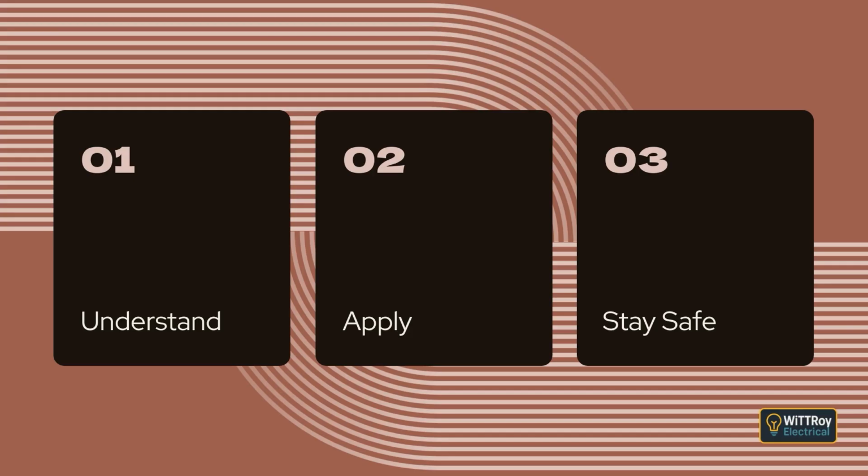Clause 2.6.3.4, Alterations, additions and repairs. Clause 2.6.3.4 explains that when a switchboard's circuit protection is replaced, the new arrangement must include RCD protection for all the final subcircuits supplied from that switchboard, if required by Clause 2.6. Any new socket outlet added to an existing circuit must be protected by an RCD.